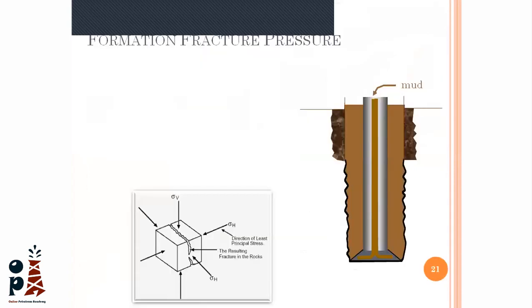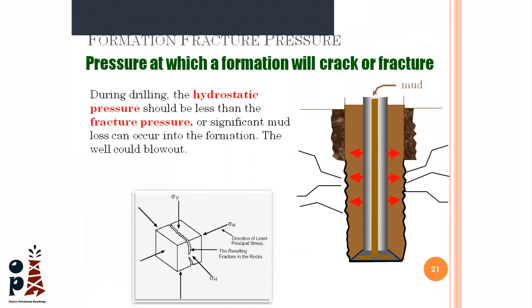Okay. The fracture pressure, I talked to you about it. It is the pressure at which I will break down the formation. There are a lot of details regarding the fracture pressure in this slide, but it is not our scope. The vertical stress, the minimum horizontal, the maximum horizontal, would take too much time to describe. So I will be satisfied with the concept of the fracture pressure, which is the pressure at which the formation will crack. And we discussed how we calculate it when we are drilling for the first time in any exploration area. We use the LOT, the leak-off test, using the cement unit: close the well, pump a little bit, a quarter barrel, and see the pressure response.